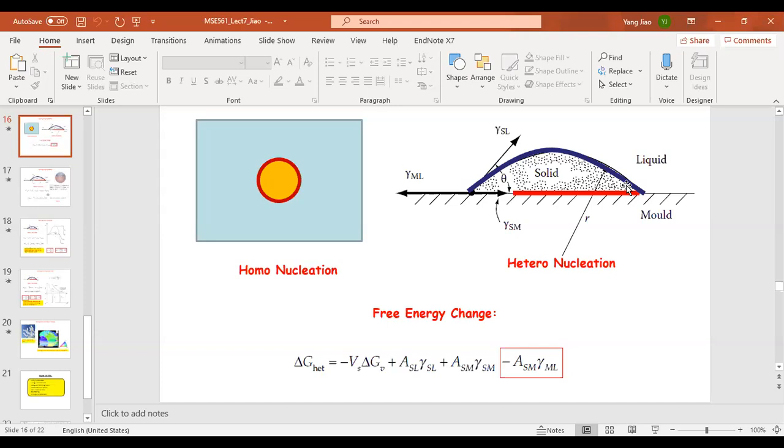So this observation suggests that it's much easier for the nucleus to form in a heterogeneous manner than a homogeneous manner. Because it's much easier for the nucleus to form via heterogeneous nucleation, this indicates that heterogeneous nucleation requires a much smaller barrier for nucleation, and we worked out the mathematical detail, or at least outlined the way to work it out. So again, we consider heterogeneous nucleation and analyze a system like that. It's a little bit more complicated, but still we can understand what's going on here.